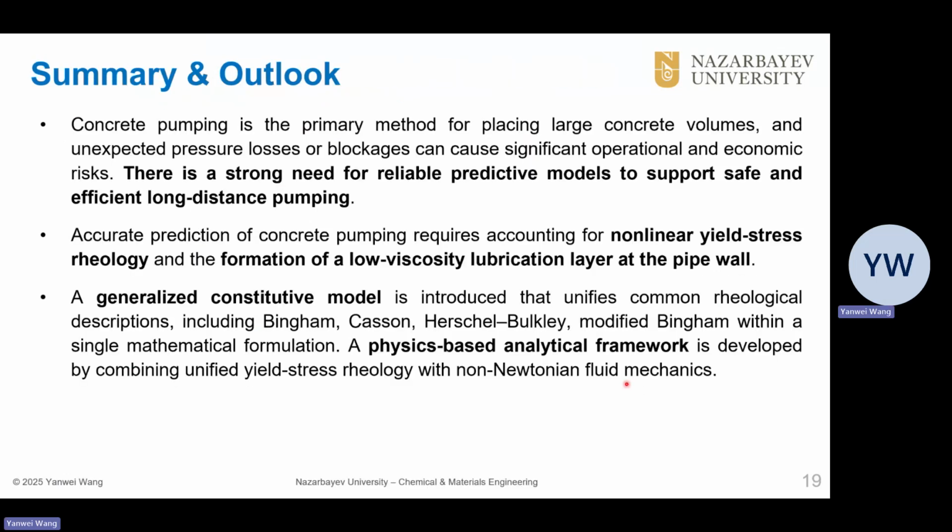To summarize our work so far, to our understanding, reliable pumping prediction requires two key physical elements: nonlinear rheology of the concrete and also the lubrication layer formation. Based on that understanding, we have developed an analytical framework that unifies rheology and non-Newtonian pipe flow to derive predictive pressure flow relations.